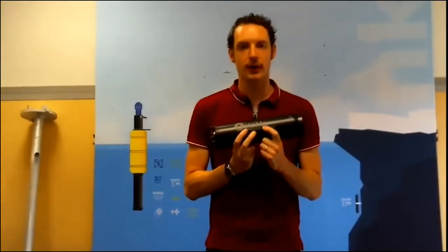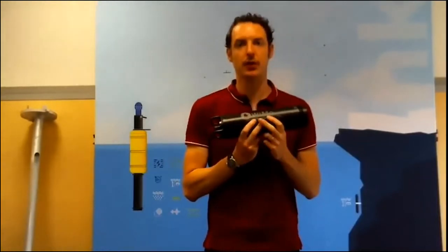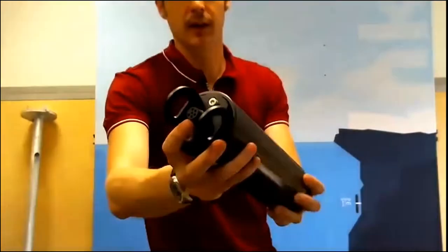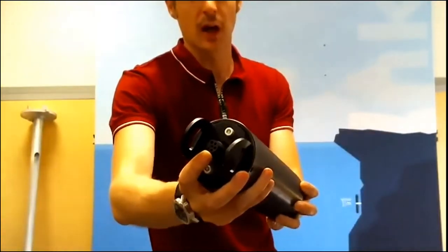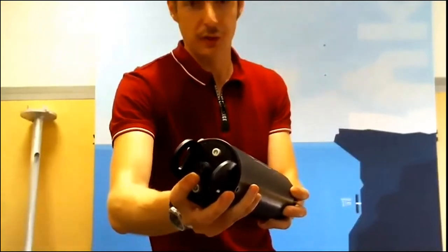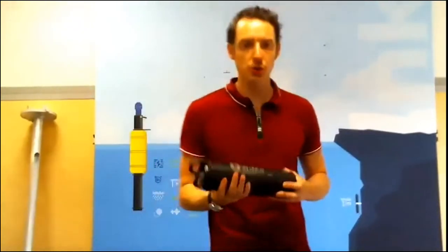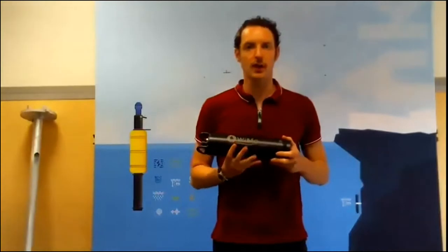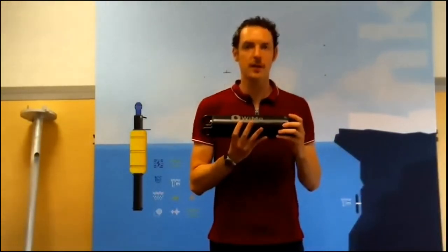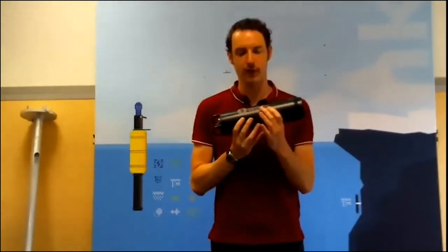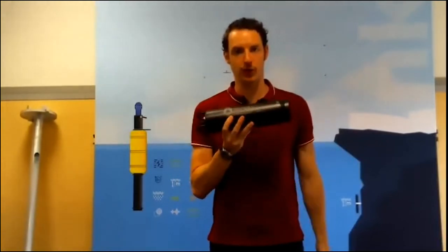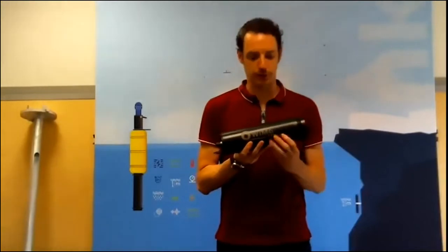Mo stands for Modbus, because the WiMo, through a Subconn connector on the back, can receive power and also communicate through Modbus, and it has a user-selectable serial link. It can be RS232 or RS485 without any modification, so it's totally modular. You can select in the interface whether it's RS232 or RS485. So WiMo stands for Wi-Fi and Modbus.